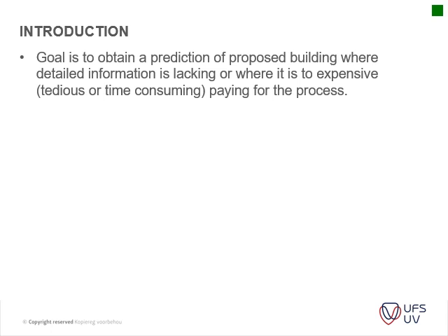It doesn't help that you try and compile bills of quantities when you're only at stage 2 or 3, because there's still a lot of things that can change. So you don't want to spend too much and pay the QS too much fees during this stage of the game. So usually estimation is the best solution that can be used.